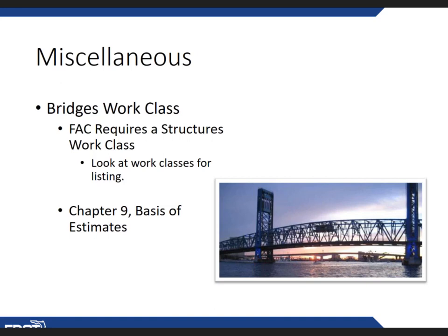I've seen people try to fudge the system by putting in a structure 00000. I've seen 9999. Don't do it. If you don't have a proper structure ID, you don't have a structure that needs to be loaded in the structures category. Follow the rules in the basis of estimates. And people are like, well, it's close enough, or the new rule is that all box culverts need to be shown in the structures plans.